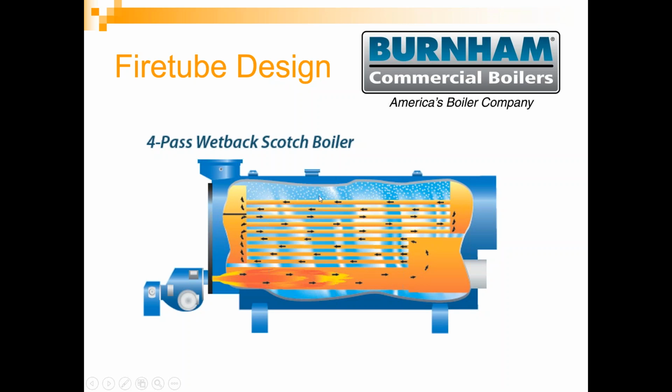There's some really nice advantages of a Firetube boiler. It's typically a very efficient type of design. Typically has a lot of water volume in that boiler. And in this type of boiler, these tubes are rolled into the header here and rolled into the back header here. So you can actually do tube replacement without needing to do an ASME code pressure repair or put an R stamp on the boiler. You can simply cut the tubes out, put in a new tube, roll it, and beat it into the front tube sheet and the rear tube sheet. It made for a very good boiler design. It was easily repaired in the field and also very efficient.